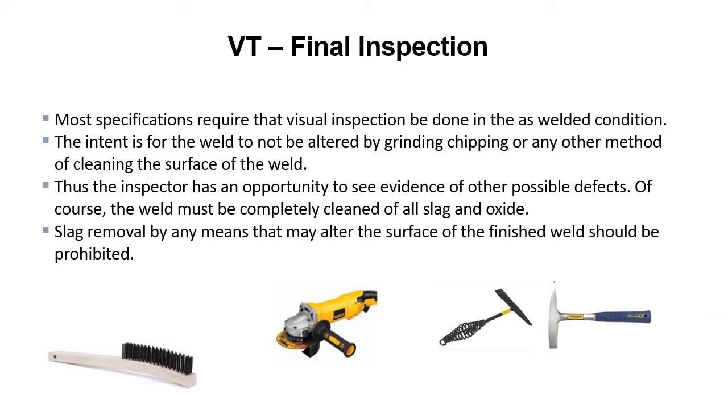Thus, the inspector has the opportunity to see evidence of other possible defects. Of course, the weld must be completely cleaned of all slag and oxide. Slag removal by any means that may alter the surface of the finished weld should be prohibited.